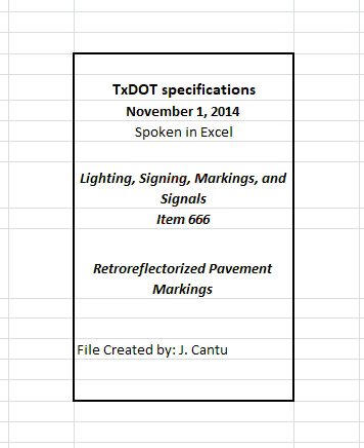The 1-mile segment will start from the beginning of the data collection and end after a mile worth of measurements have been taken. Each subsequent mile of measurements will be a new segment. Center lines with 2 stripes, either solid or broken, will result in 2 miles of data for each mile segment. Each center line stripe must be tested for compliance as a standalone stripe.